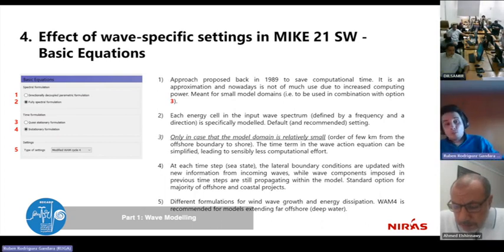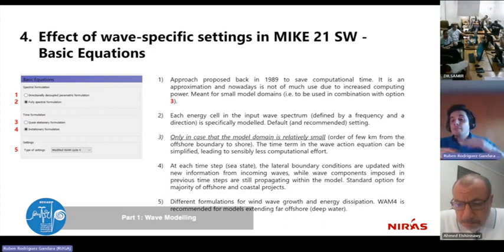So when the new boundary condition enters the domain, the previous sea state that you were imposing at the boundary has already propagated. So you don't have to deal with interaction between different things happening at the boundary and what happened at the coastline, because everything has happened in so little time that you can consider it stationary. And each time step can be taken as independent from the previous one.